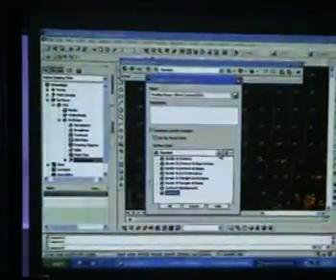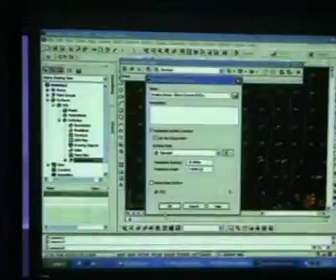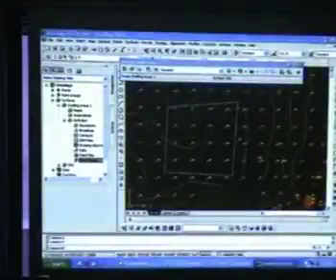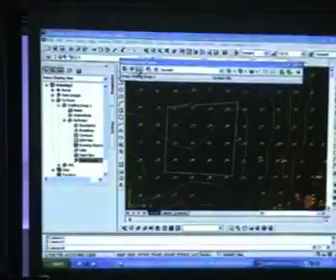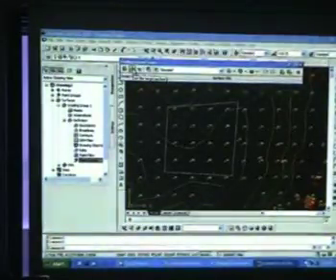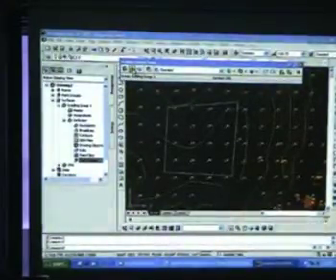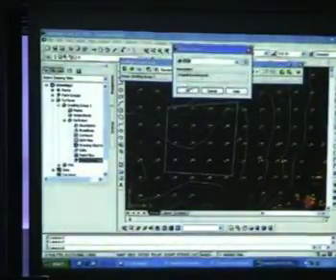Surface style, you can also give it a try later. Maybe I'll just leave this as standard first. Okay, and I'm going to click OK. So this is the surface, grading group 1. You'll find now that we have grading group 1 and the surface is OGL. Next we set the target surface, because we want to provide slopes from this platform to the original level. Just in case you have more than one, you need to specify what's the target. In this case, it's only one, OGL. It's fine.